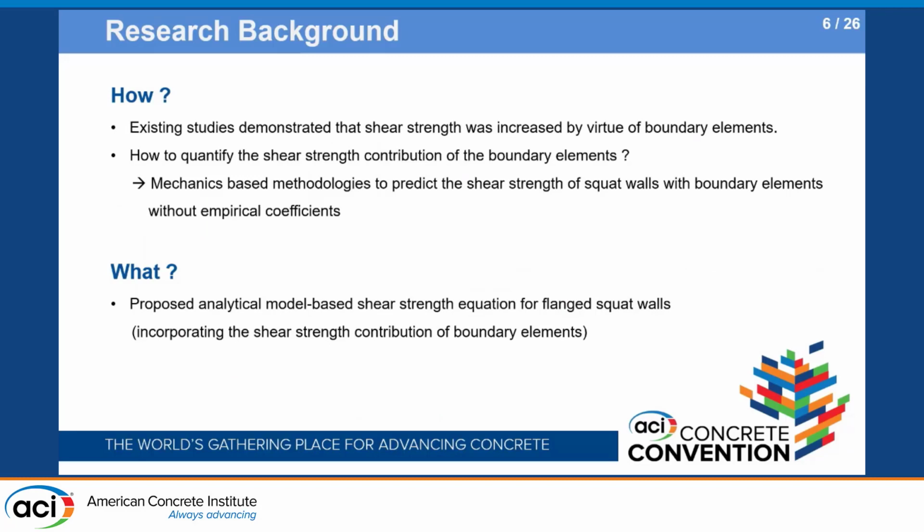So how can we solve the problem? Professor Park and I tried to develop a simple mechanics-based strength model that directly considers the influence of boundary elements, barbells, or flanges for squat walls, while minimizing the use of empirical factors that depend on data sets.